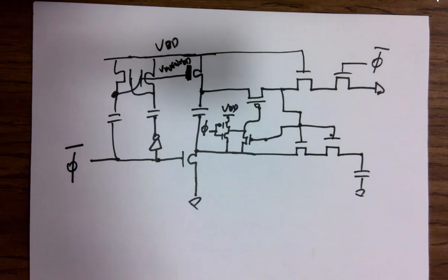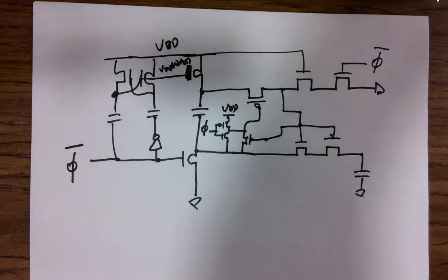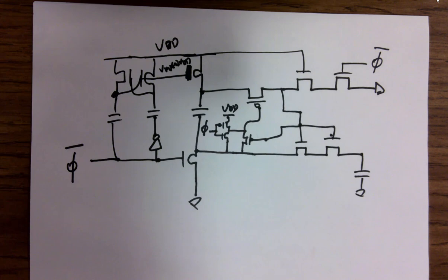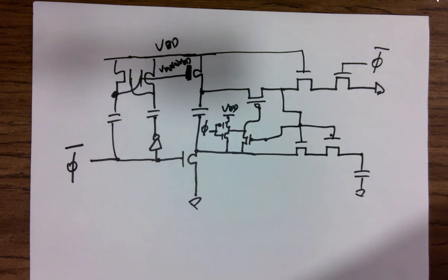You turn it on, so the NMOS at the bottom gets a channel open, and then you got a 2 VDD over here, starts dumping charges, boom, dumping on the cap. So the capacitor is like a bucket being filled with water. Are you discharging it? No. So it's staying there, and then you just cut it at the bottom, so the NMOS is off. You still have the bucket of water storing there, so it's called a floating VDD.